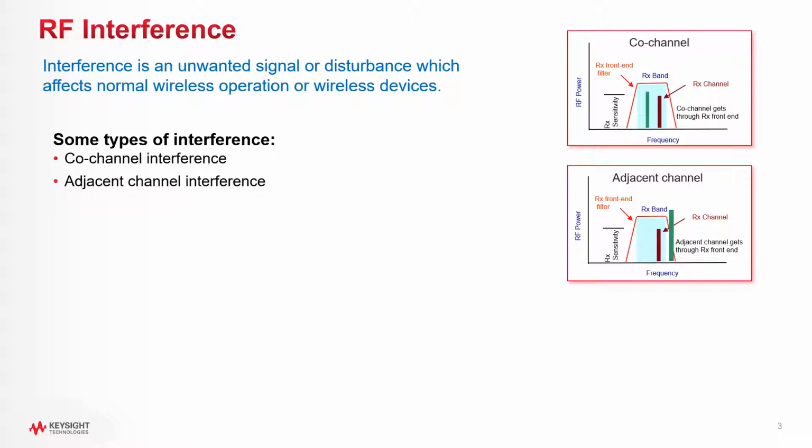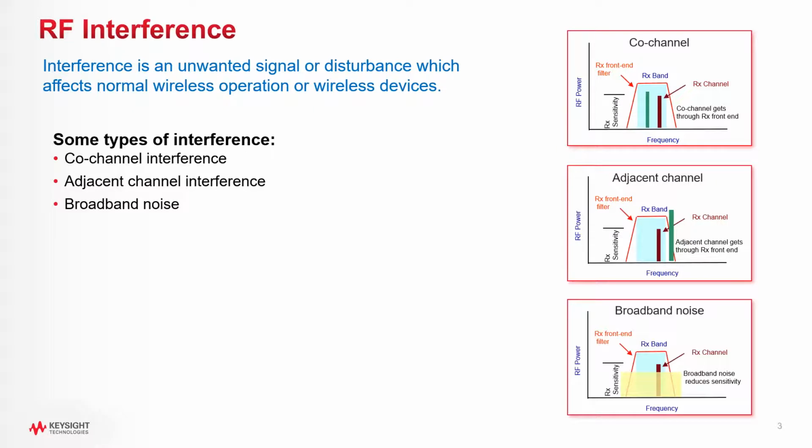Why is it so important there? Well, Earth stations are receiving extremely small signal levels because the satellites are way out in space. And so by the time it gets there, it's a really low signal level. The 5G towers are going to be transmitting at relatively high power. So even though it's not in the band, it could be that the low level skirts that go out of band are still too high level for the satellite dishes. And so that's a concern, and that would be a concern about adjacent channel interference.